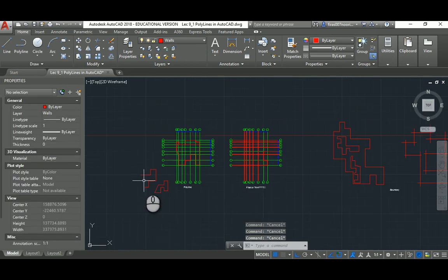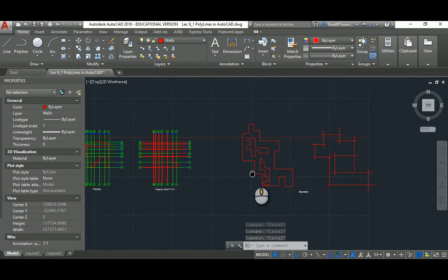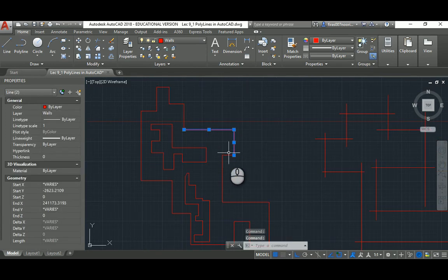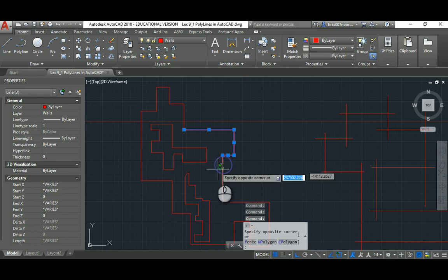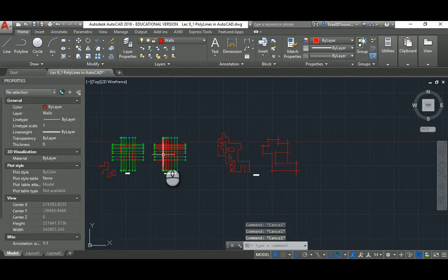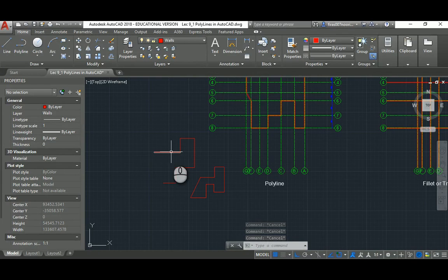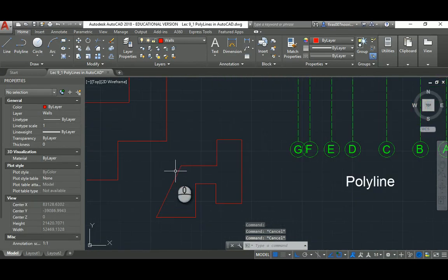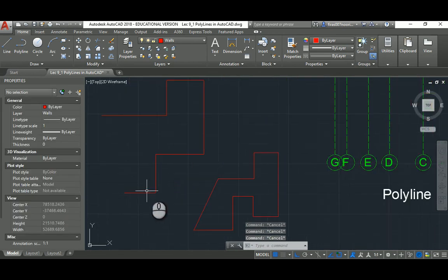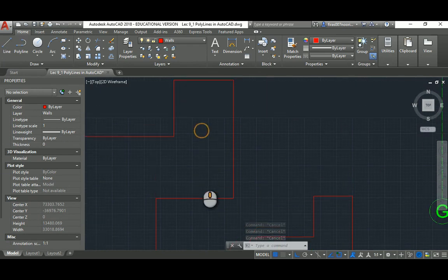So here, for example, is also a group of separated lines that I created out of a polyline, and then I exploded it. For any line or any polyline that I explode, or even any group of lines, like this one, I can just turn any group of continuously met end-to-end lines into a polyline.